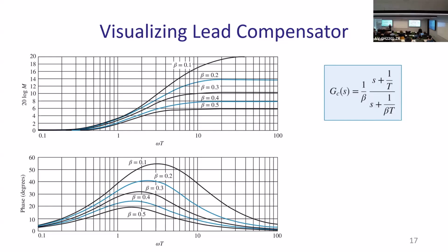And this is why initially I'm designing my DC gain separately and saying I will achieve DC gain or KV, or whatever constant you choose, depends on what type of transfer function you have. Give me the steady state errors that I want. And then I will design that controller assuming that I'm not touching the initial point of omega equals to 0, right? This is the overall idea.